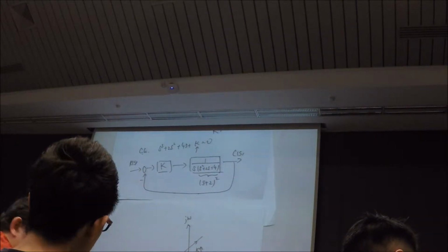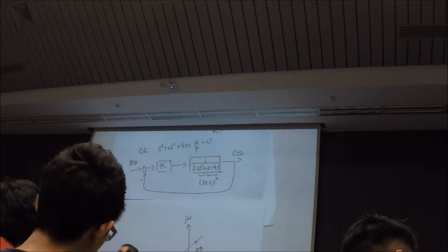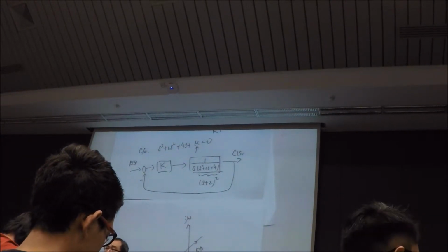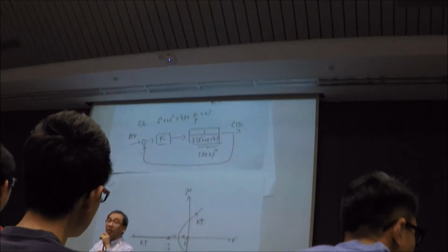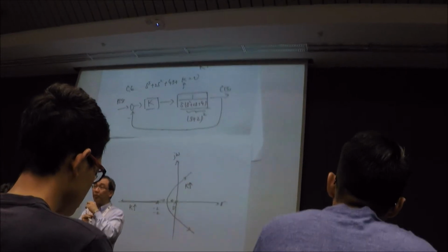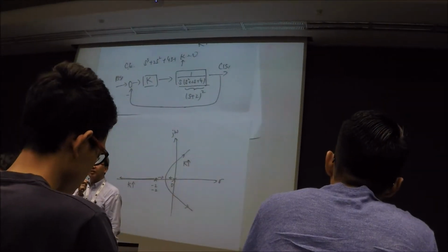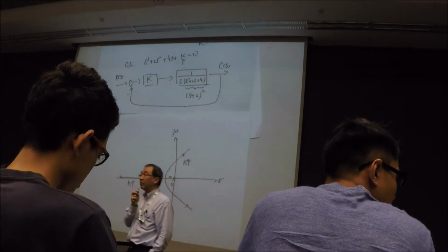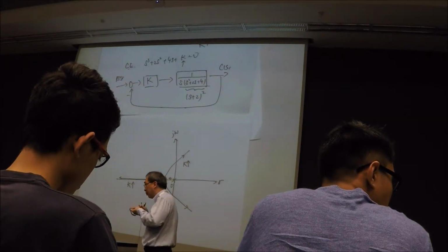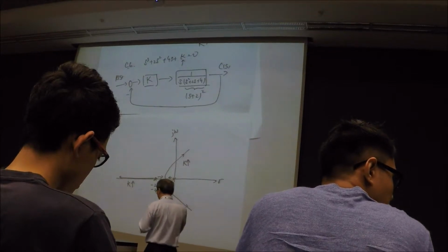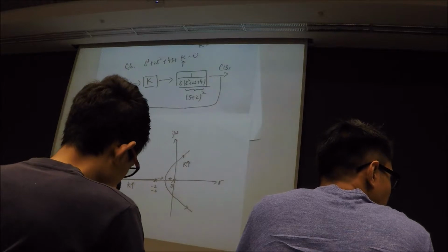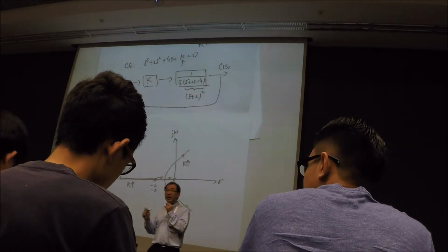And I can show you later on, as I mentioned many times before, we talk about your second order system and third order system. Why second order system? You're not so afraid of instability, okay? Because once you learn the root locus, I can show you quite easily. Whereas third order system, without fail, you will run into instability problem if you are not careful. Okay, so that's what we mentioned before, right? When we talk about your stability analysis and all that. Okay, all right. Any question?